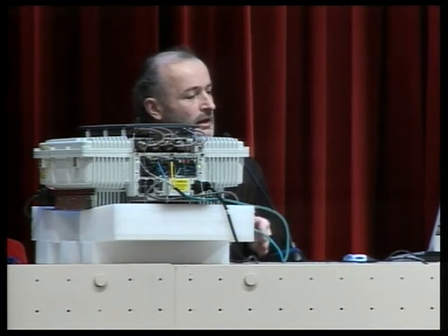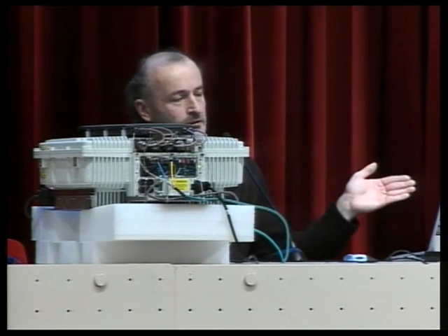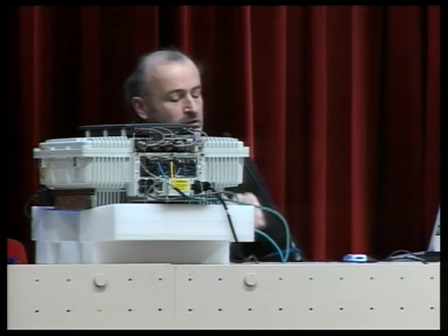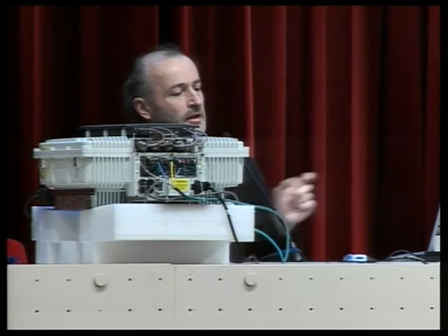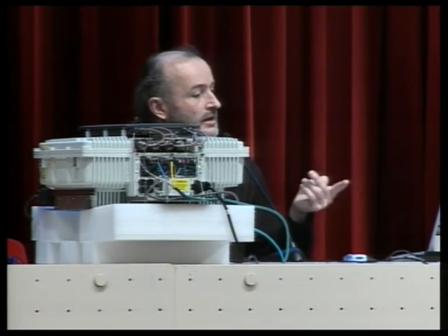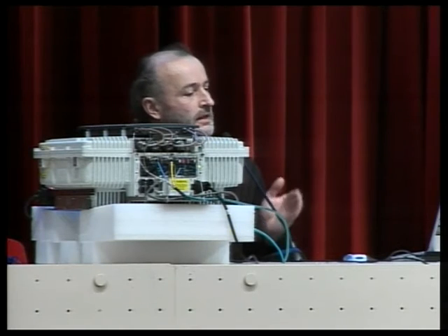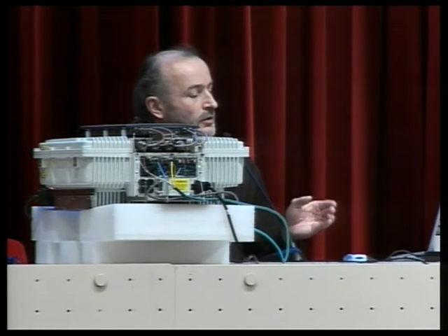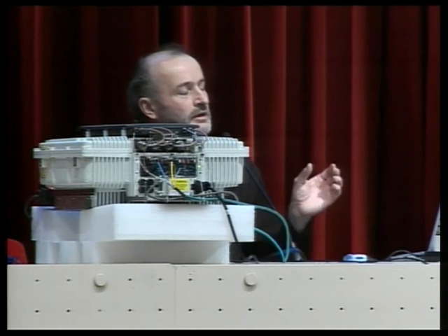This stream does not have any synchronization marks. You just have this data stream and you have to search for the synchronization by yourself. You don't see speech is starting, speech is ending. You have this data stream and you look in it for where the package starts and where the package ends. And then you have this package, which in GSM is encoded and holds 20 milliseconds of speech. This 20 milliseconds of speech is repeated with 50 hertz frequency, so you get a continuous stream of single packages of compressed speech.